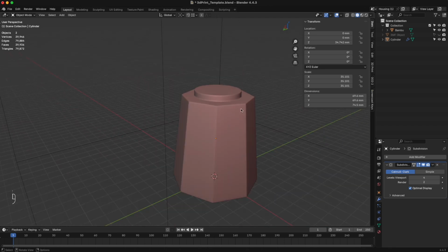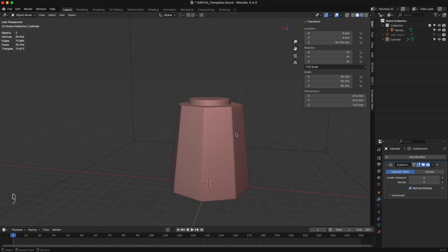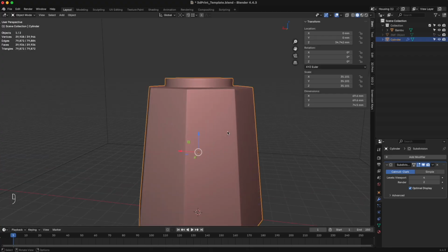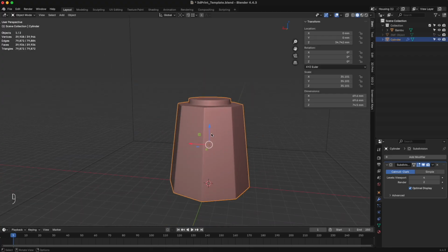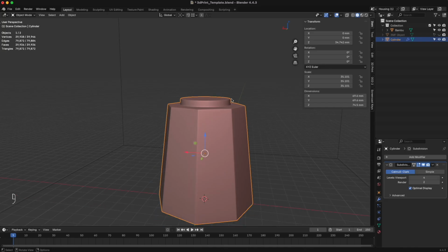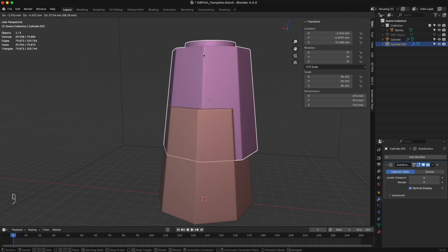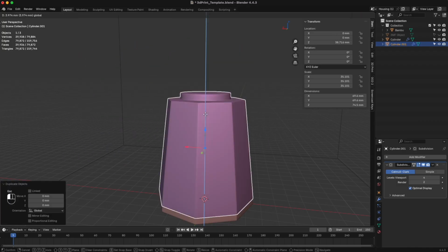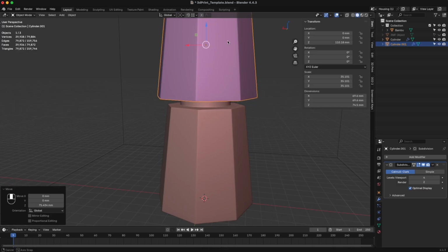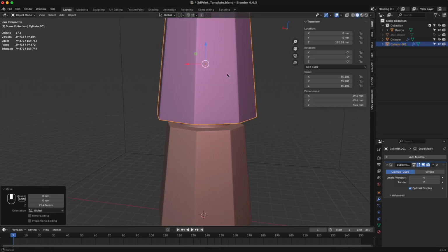All right, so there's our bottom. We're just going to be mega scrappy here. Now I could use a mirror modifier to create a clone of this object, but we're just going to go Shift D, and it's stuck to your cursor. If you just hit Escape and then drag it up, that's probably the best way to move this object.